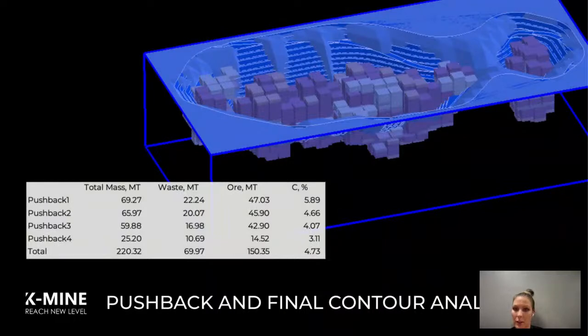So the best indicator for assessing the implementation of the design of the pushback is the deviation in volume and mass of rocks. We compare geometric, volumetric, weight, and quality parameters. And the allowable deviation is considered to be for ore minus 5%, since the lower part of the pit is most often not possible to work out because of its width, and plus 10% for overburden, since the addition of roads, ramps to the project as a rule entails additional justified volumes of rock mass excavation.